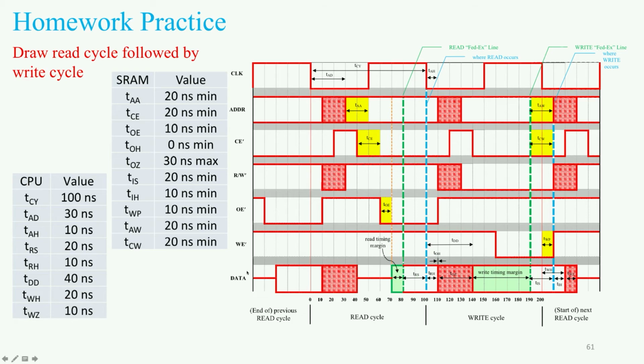Now let's take a look at the data bus. We have transitioned the data bus all the way up to this point. The read ended. The SRAM flipped up the OE bit here. There was no hold time. Then there was this transition to high impedance time. Now we have to figure out when the data bus is going to be used properly for the write.